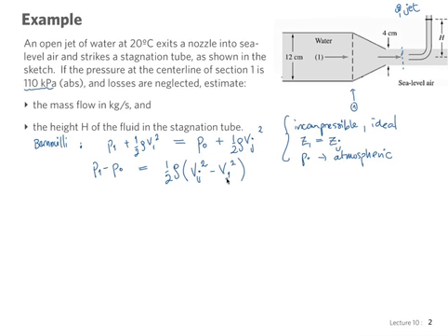Conservation of mass. Very good. So conservation of mass, or continuity, will help us deal with these 2 different velocities that we don't have there in this equation. So let's just write in the simplest possible way, A1 V1 equals A of the jet, V of the jet. Now we look back at our diagram and we realize that we're actually given the diameter of the pipe and the diameter of the jet, so we're in good shape in that sense. We can immediately rearrange these things a little bit.